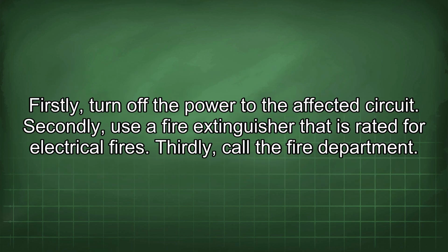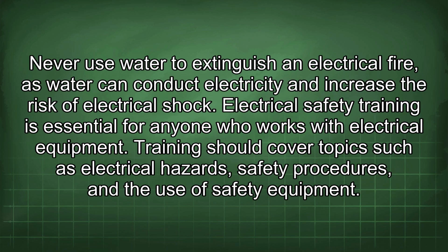Firstly, turn off the power to the affected circuit. Secondly, use a fire extinguisher that is rated for electrical fires. Thirdly, call the fire department. Never use water to extinguish an electrical fire, as water can conduct electricity and increase the risk of electrical shock.